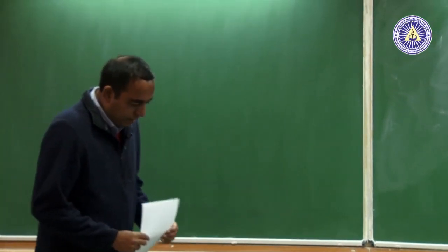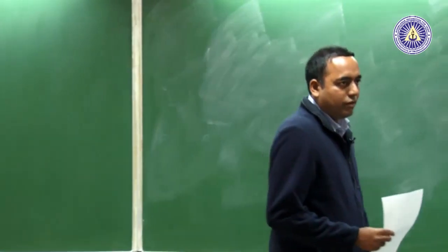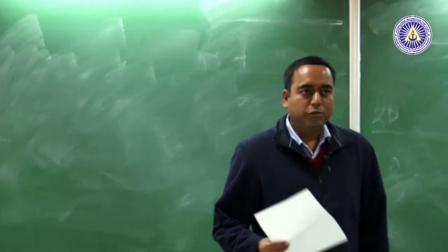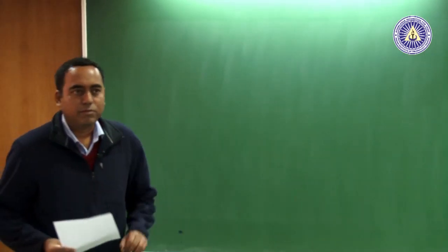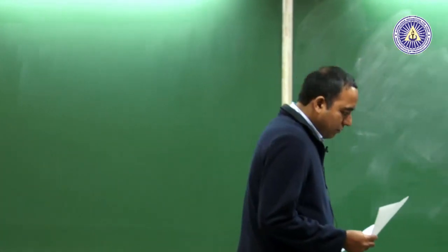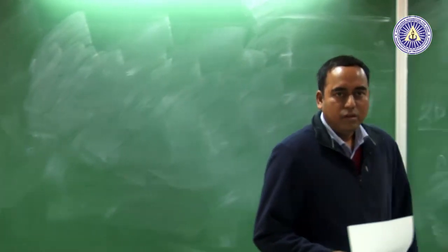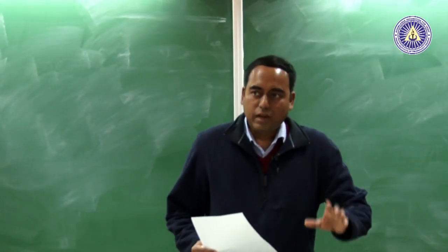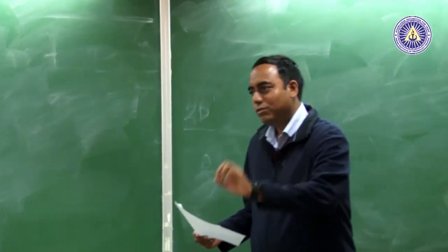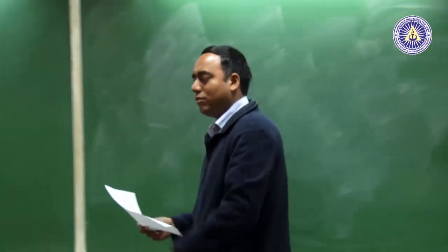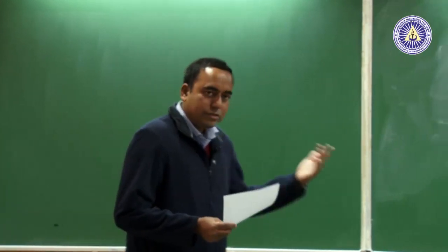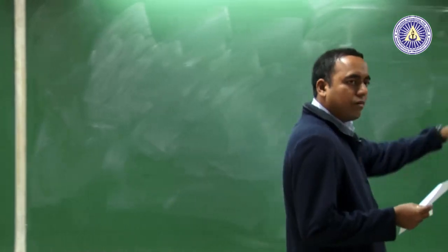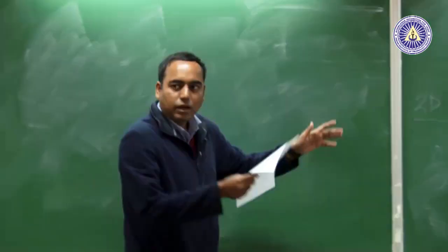Now, the typical ways to poke a non-Newtonian fluid, if I ask an infinite number of people, there would be an infinite number of ways. So, what rheologists do and what non-Newtonian fluid mechanicians also do is they choose a set of flows called standard flows. So, when we have an unknown non-Newtonian fluid, we have a certain set of flows which are standard, and we only use those flows and impose those flows on the sample of non-Newtonian fluid, and then record the response of that fluid, and then try to understand from the response that it generates what sort of a non-Newtonian fluid it is. Like, is it close to this family or that family or that family.